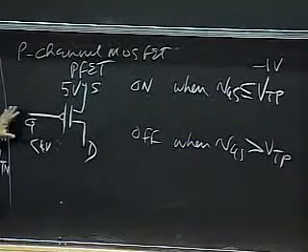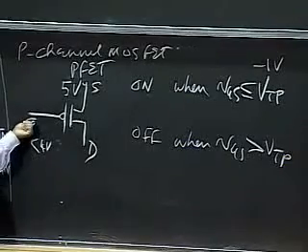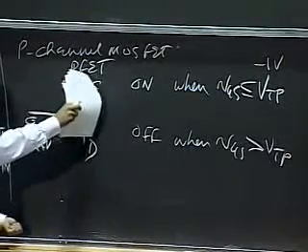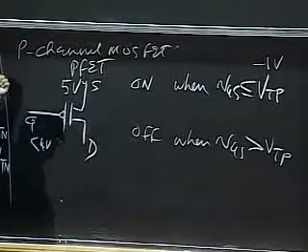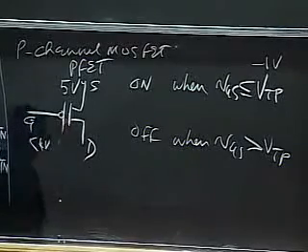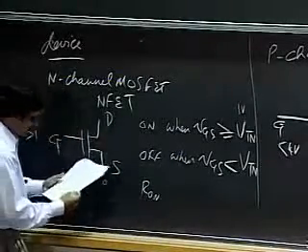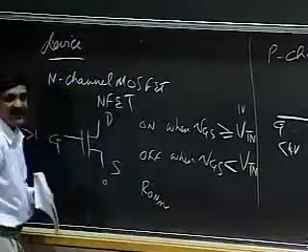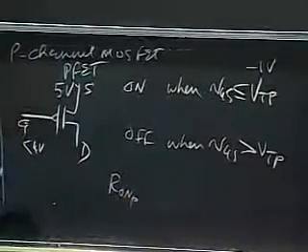Okay, so this is a complementary device that I postulate that behaves in a complementary manner. So the gate voltage rises, this guy turns on. And in this particular situation, when the gate voltage drops below the source voltage, this guy turns on. So one is the rising guy that turns on. In this particular situation, when it falls, the gate turns on and shows some resistance. In this case, the resistance would be R on. And to show that it's N-channel, let me say N. And in this case, the resistance when turned on would be R on P to represent P-channel.